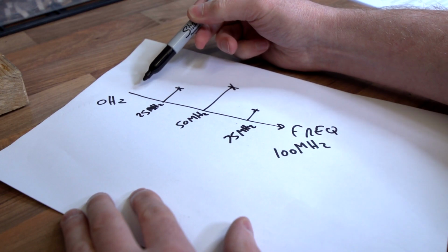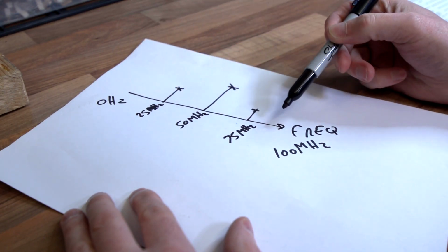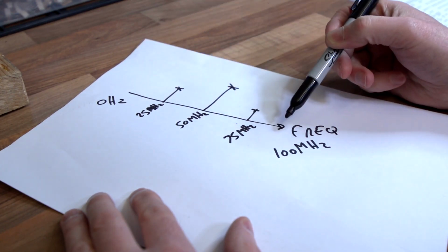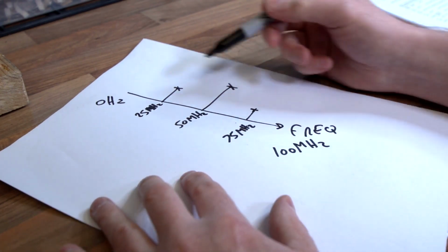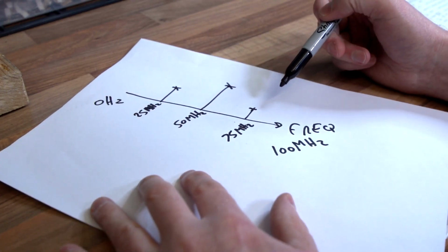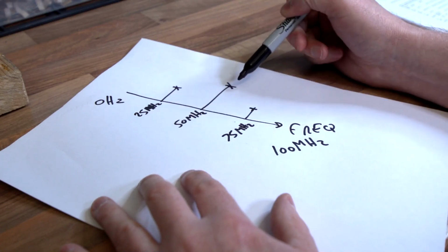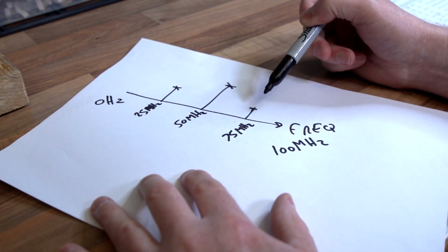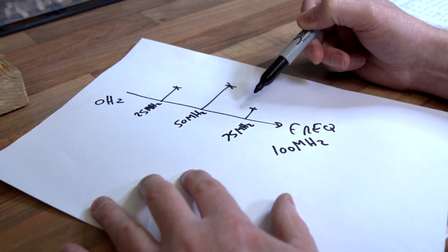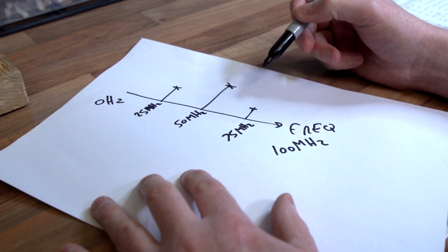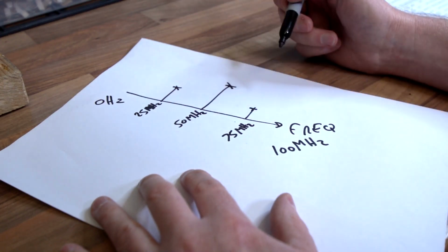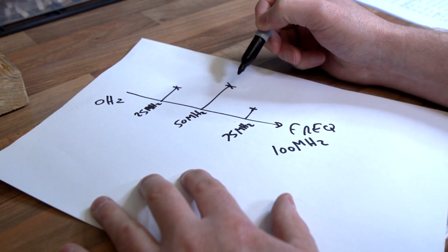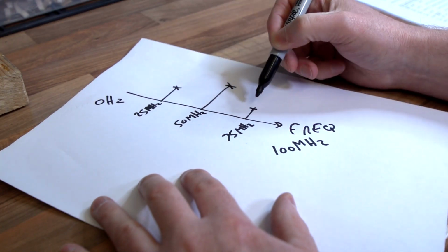As the frequency of the signal that we're measuring increases, we see it displayed along this x-axis. Now that's actually interesting to know straight away by looking, it allows you to display carrier signals or where the frequency of a signal generator is set to. But what you can also do from this is determine the amplitude, which gives you the signal level of the peak that you happen to be looking at.